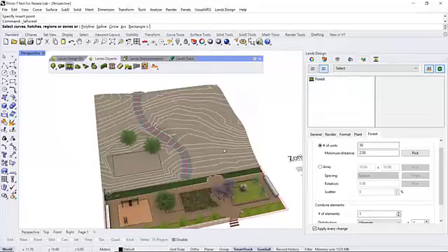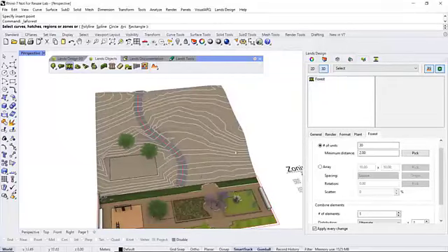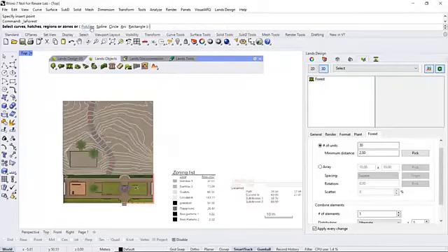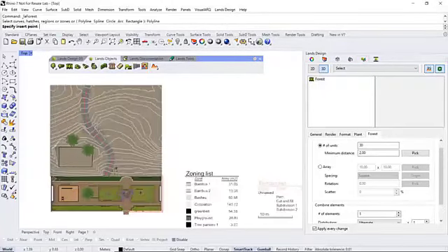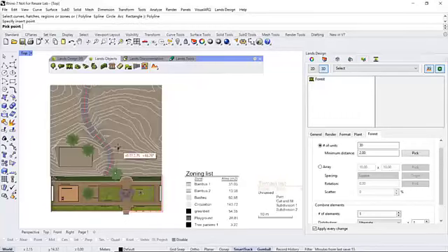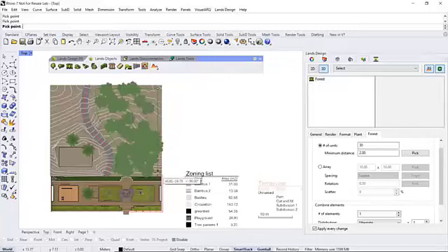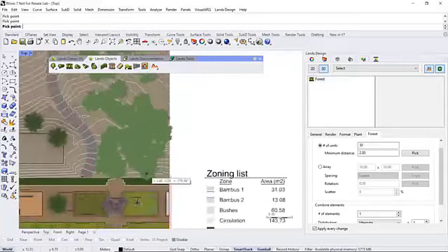And finally, we can either select an existing contour, or we can draw it on the fly. So I'm going to draw it from the top viewport, and I'm going to use any of these options available here. So maybe polyline, and you will see that as I am defining this contour of the forest, the elements are already inserted.